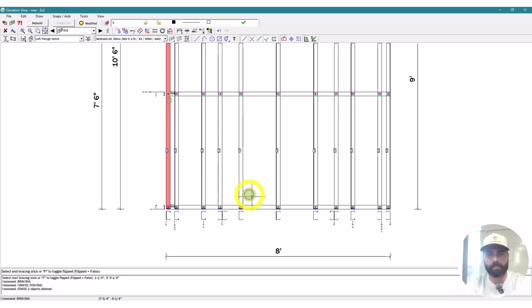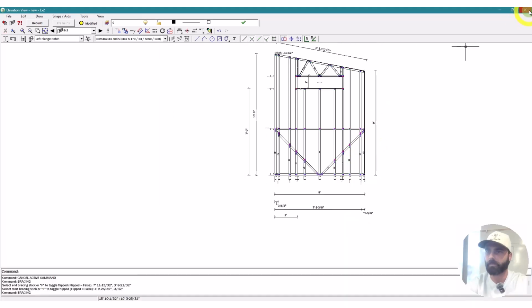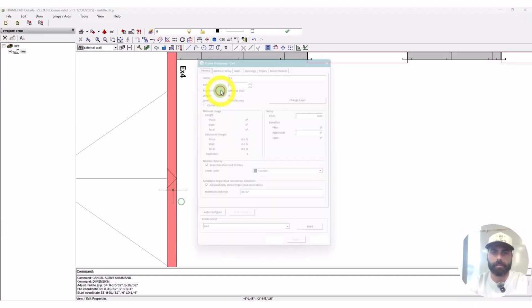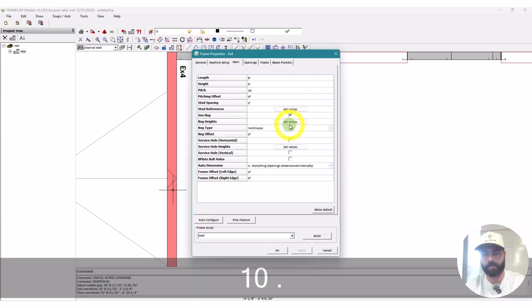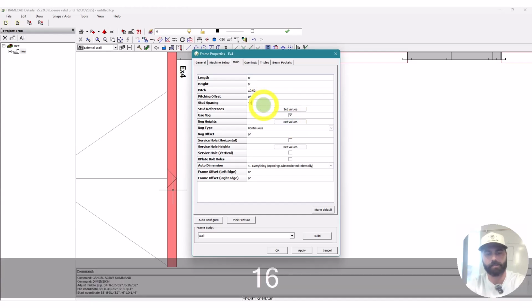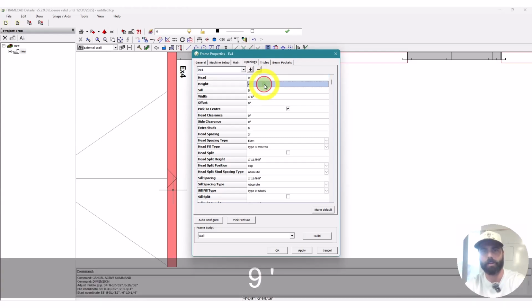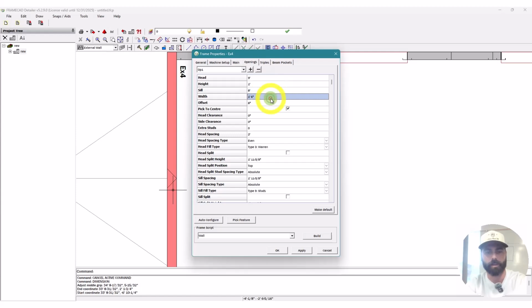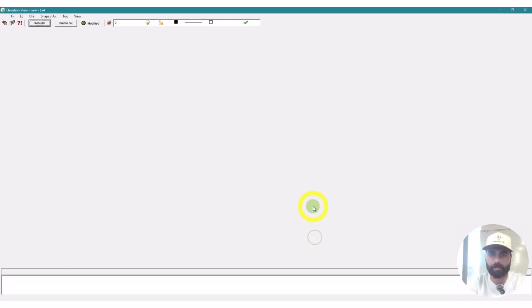We'll jump over to the tongue. This will be a 9-foot wall at a 10.62 degree pitch at 16-inch centers. We'll go ahead and add that same opening on this side. So we said it was 9 foot. We did a 1 foot opening with 4 feet, offset 2 feet. And we'll go ahead and build this. We got to do the same. And we'll do this, sill spacing at 16 inches.